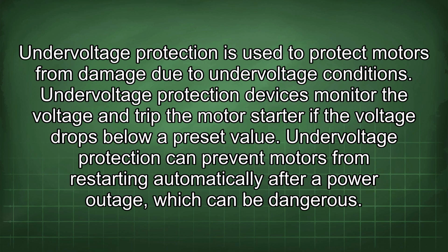Undervoltage protection is used to protect motors from damage due to undervoltage conditions. Under-voltage protection devices monitor the voltage and trip the motor starter if the voltage drops below a preset value. Under-voltage protection can prevent motors from restarting automatically after a power outage, which can be dangerous.